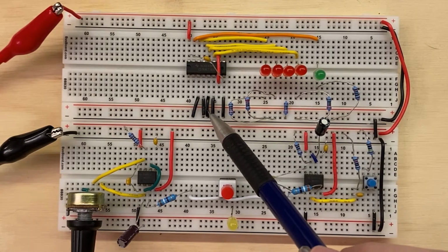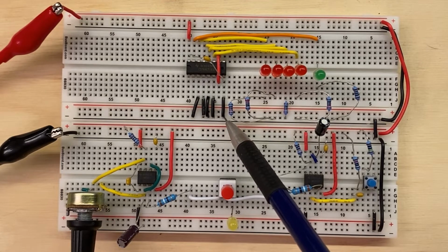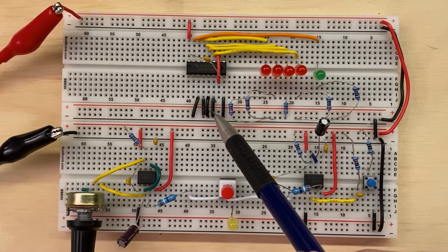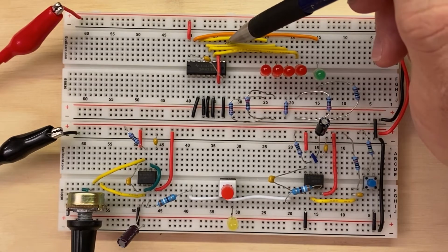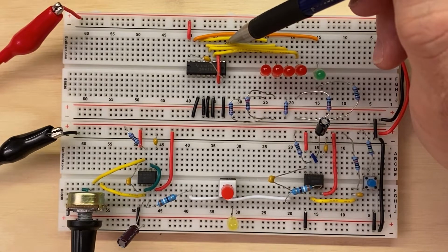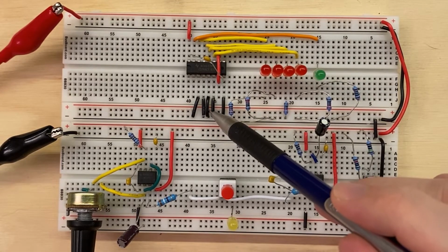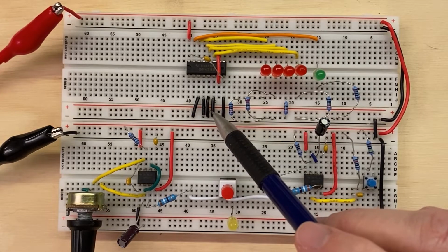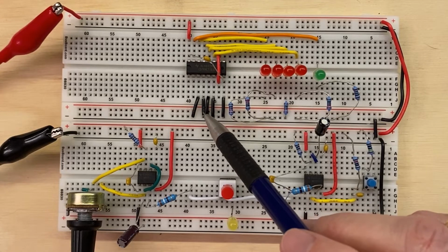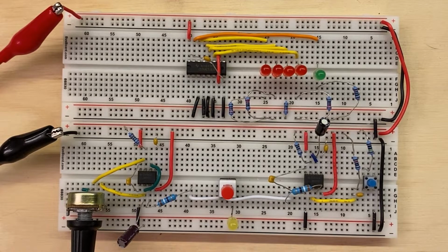And right here, you see I have 4 grounds. This is the normal ground for the power, but these 4 grounds are for the P0, 1, 2, 3 inputs. And our SPE pin is right at the edge here. So if this is ever set low, then all it's going to do is load zeros into the output. Now, I'm not going to really use the load, at least yet. But I still tied them low because, you know, for chips, you never want to leave the inputs just floating. You want to set them high or low. Even if you're not using them, you want to put a value on them. You just don't want them floating around in the air.